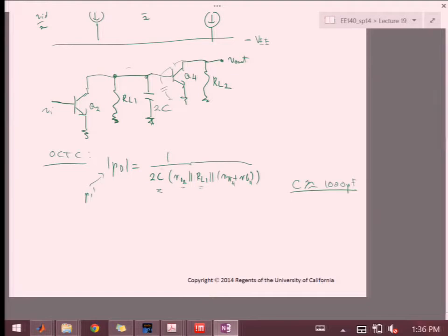So in order to decrease this cap, instead of placing it like this, we could try to use the Miller effect. All that the Miller effect says is, if I have an amplifier and I have C over here, or any impedance, we covered this kind of when we did single stage stuff, then this is equivalent to having some other C here lumped to ground and A. At least at this node, the equivalence is that this has to be something like this, right?